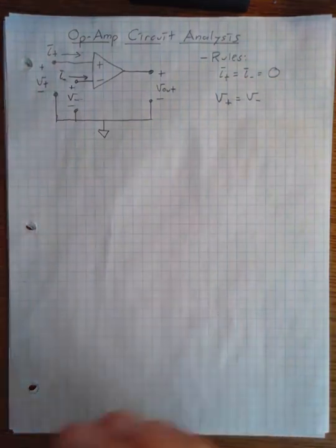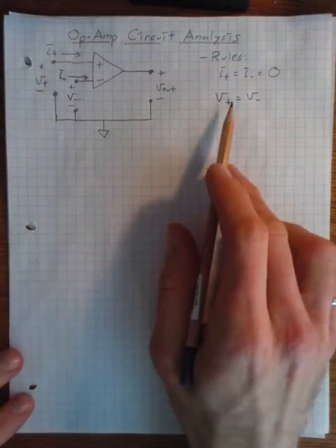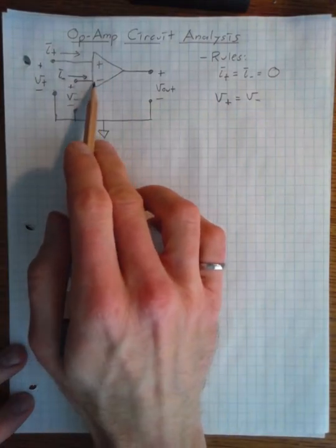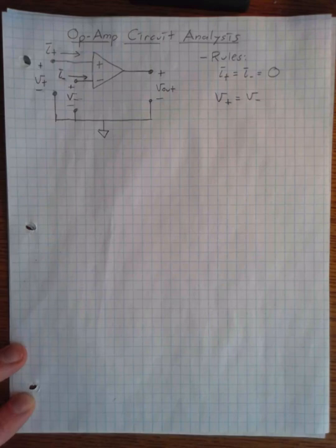And so there's just something about an OpAmp such that we can always assume that it forces our circuit to behave in such a way that the voltage at the positive terminal is equal to the voltage at the negative terminal. I'm not going to explain why that is. That's the purpose of the lectures that I have coming later on in my Circuits 2 series. And so let's just take this as a given for now, and we'll use these rules in circuit analysis.